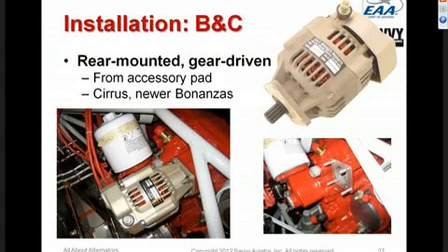It's designed to mount on an accessory pad where the vacuum pump would normally mount, except that in aircraft that use these backup alternators, typically they're all electric airplanes that don't have a vacuum pump, and so this little B&C standby alternator mounts right on the accessory pad where the vacuum pump would normally mount, and is driven off that pad.